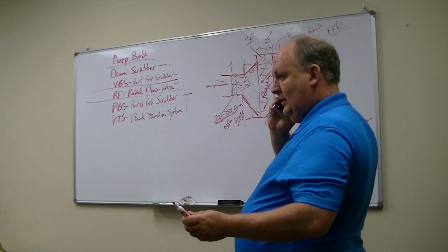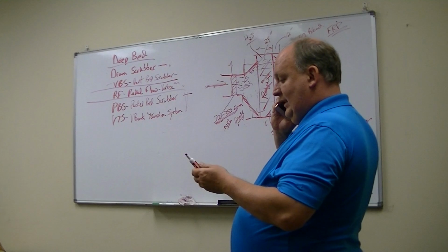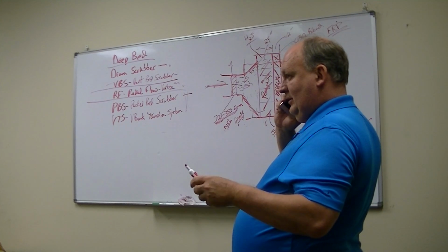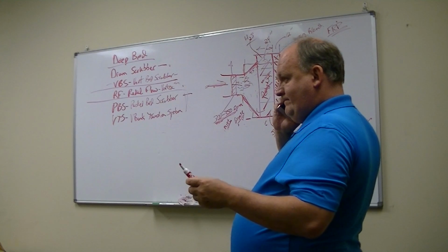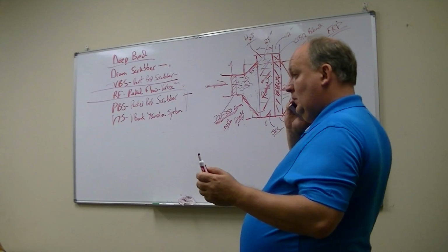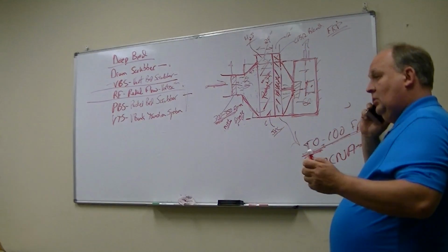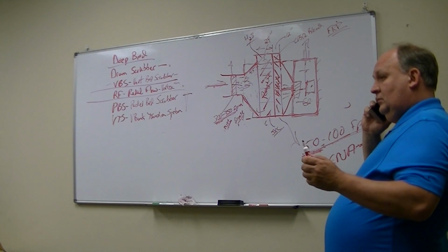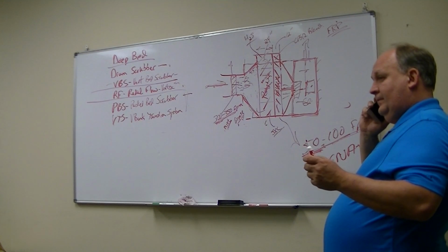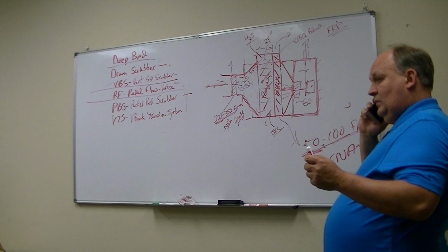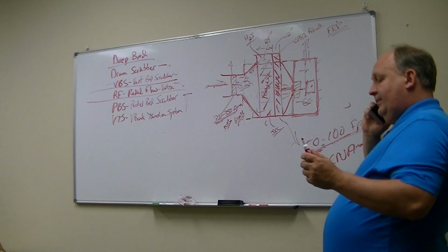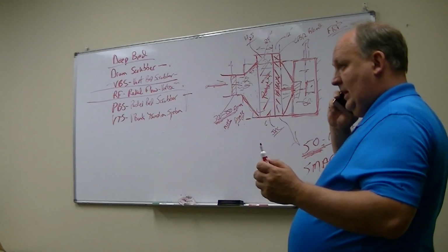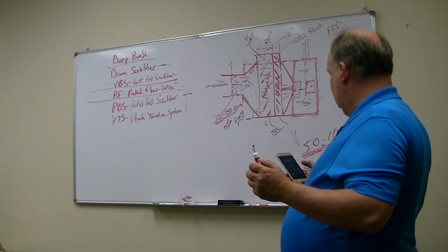Anytime you have a plenum fan like that, you need to make sure that you order a cone that goes along with it. There needs to be a plastic cone that the wheel is basically going to go into. It's mounted to the back side of that wall. Where you have the fan right there, there's a cone that actually inserts into that and goes against that wall. So when you're ordering your TEK wheels, you get those cones.